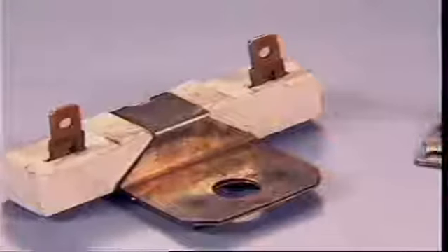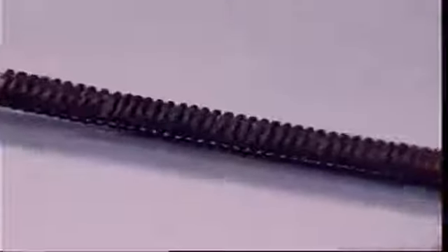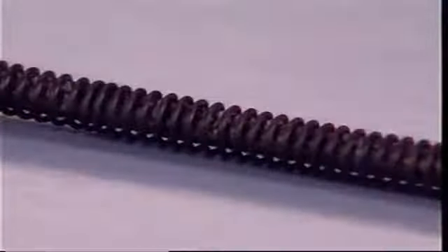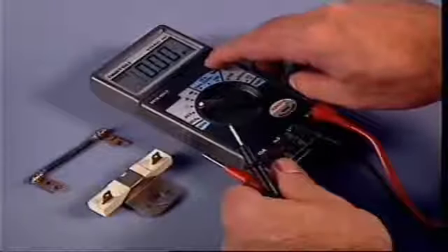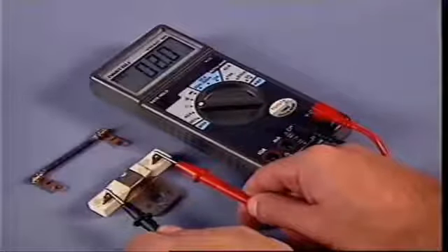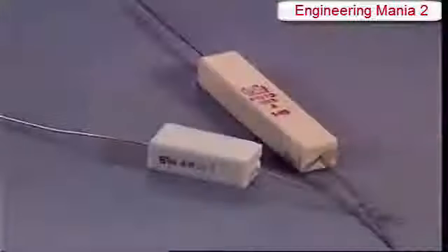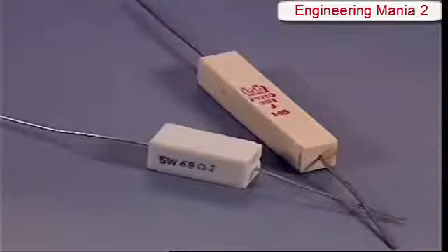Most resistors that can carry large currents contain a coil of high resistance wire wound around a ceramic former to dissipate heat. Resistance is measured in ohms, represented by a Greek letter omega. And so resistors are rated in ohms as well, to indicate how strongly they will oppose any current flowing through them. Resistors also have a wattage rating. This is because resistors work by converting some of the electrical energy passing through them into heat.